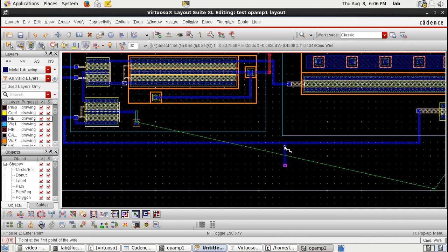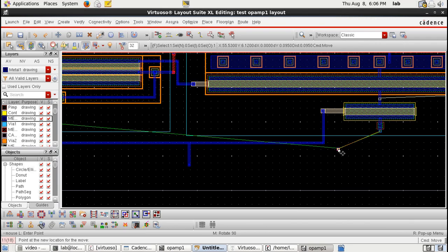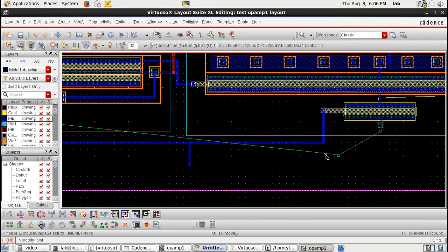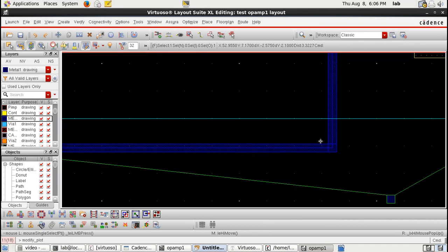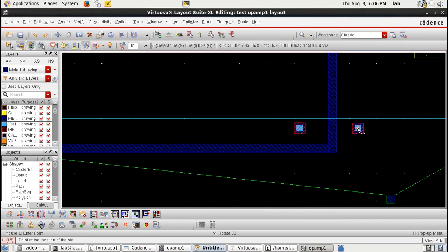the other pin that is of importance to us is the VSS pin, and you can see that it is also going to overlap in this particular case. So I'm again going to put a via. So let me put a via here, and let's create a metal 1 to metal 2 via for this place, and let's just take a metal 2 wire and connect it to this.